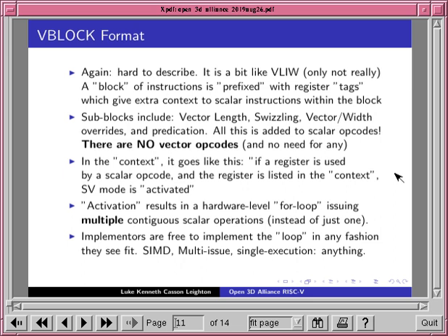Texas Instruments used it in particular, and also the Mill architecture uses tagging, but they do it in quite a different way. It's a bit like VLIW, only not really, because those instructions have a sequential context that must appear to be in sequential order, just like in scalar operation, whereas VLIW is a simultaneous thing.